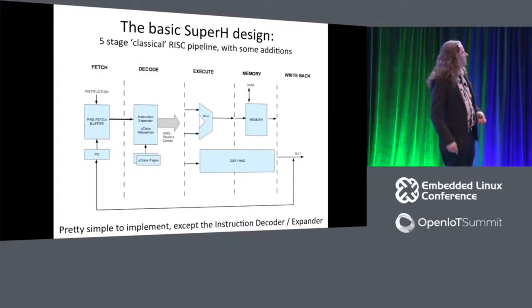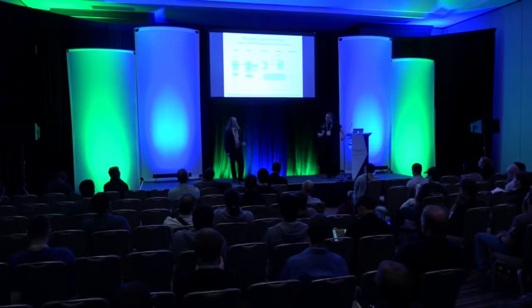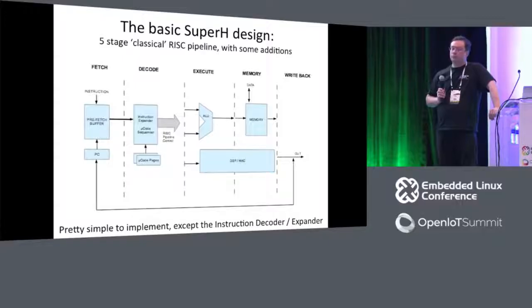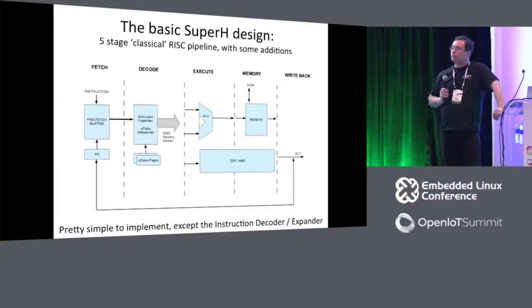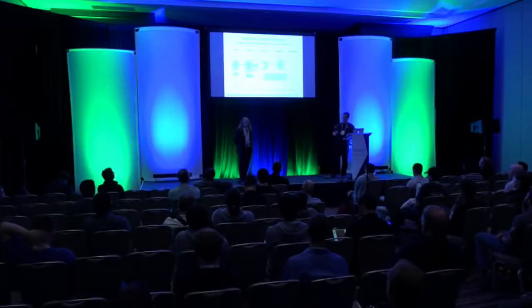Next slide. On the memory side, the original SH2 had 1 instruction bus. That was an architectural mistake. It makes things pretty nasty. But maybe when we get into the instruction set, if there's time, I'll show you why they did that. We run the same software. We're not necessarily the same implementation. We fixed some stuff. I believe you can do unaligned access with us that you couldn't in the original, for example. Right. The DSP and MAC block in here is essentially a separate coprocessor.